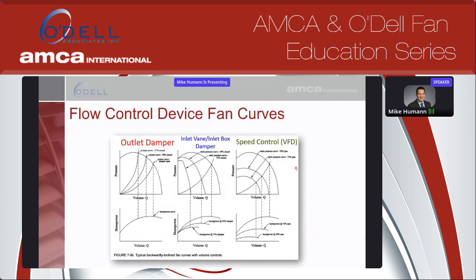So we talked about how the fan curve changes. With the outlet damper, when you have a fully open damper, as you close that damper, you actually ride back up the fan static pressure curve. As we start to close it, you'll see that we're adding pressure here and cutting our flow. So we're increasing pressure, and that's the added resistance the outlet damper is creating, and you're cutting down flow. That's how the outlet damper affects the fan.